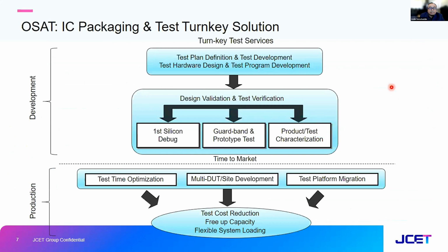So in a general perspective, most OSATs will offer this kind of service in terms of the packaging and also test as a turnkey offering or solution. They will offer the packaging and also test, but in this illustration, I'm focusing more on the test. So as mentioned earlier, this test plan definition with the test development group or engineers is to define the test hardware design and the test program development. Those are the very important things to do right from the beginning.